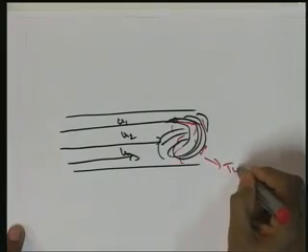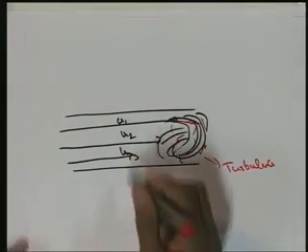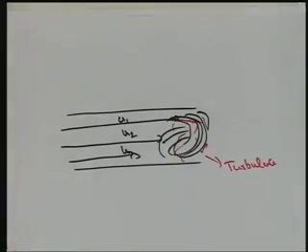So, this region is now turbulent. This turbulence which is generated is called free turbulence. Here, as you can observe, there is no specific reason for turbulence other than the different layers. What happens is that the velocity changes and then turbulence is generated. This is called free turbulence.